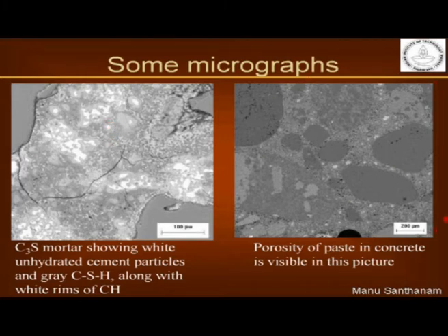If you look at the concrete image under the microscope, you see several large aggregates, smaller aggregates, and the zones in between occupied by cement paste. Now the thing is, if you look at the overall picture of concrete, about 80% of your image seems to be only aggregate, only 20% of the volume is looking like cement paste, and that is exactly what you have in normal concrete, that only 20% of your normal concrete is actually cement paste, the remaining is just aggregate.